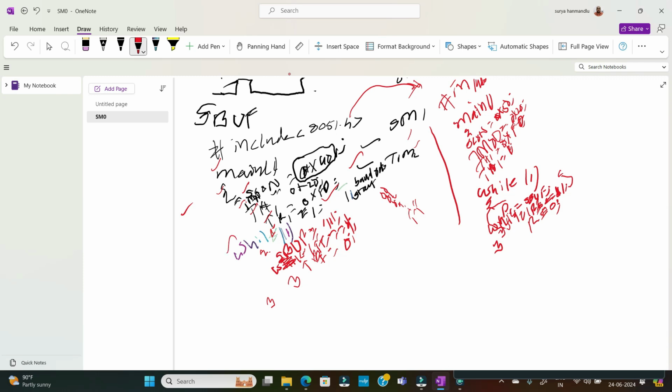In the while(1) loop, we put our desired character, which is H, that I want to transmit, and we have to wait until the transmit interrupt flag becomes 1. So we write while TI equal to 1, then immediately we make capital TI to 0. Close the while loop and close the main method.